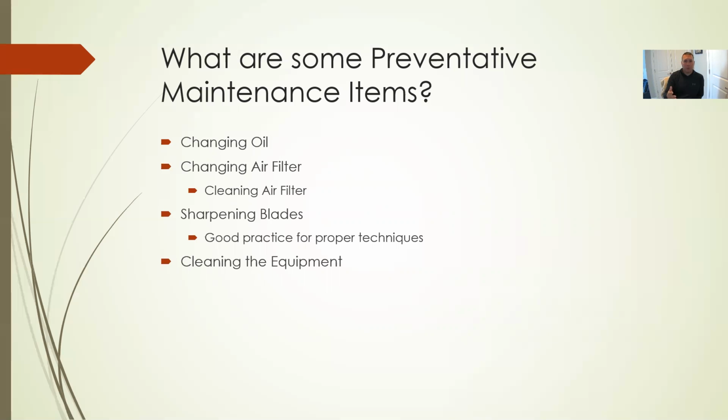Not much dirt is going to get in the oil filter. The air filter, though, if you're getting dirt and debris in the air filter, you got to clean that out, right? You got to either blow it off or replace it. It's an inexpensive part, but helps the life expectancy of that equipment run properly, right? It's not going to be as hot, and it's going to allow that engine to cool itself.